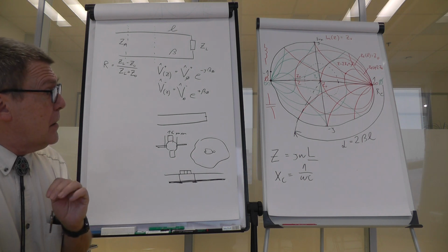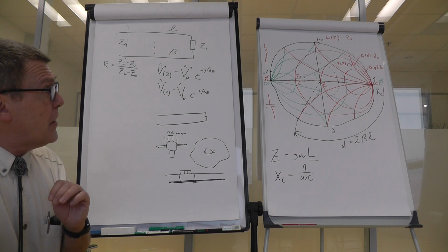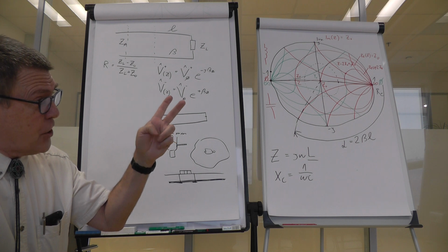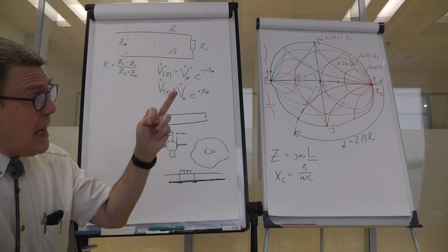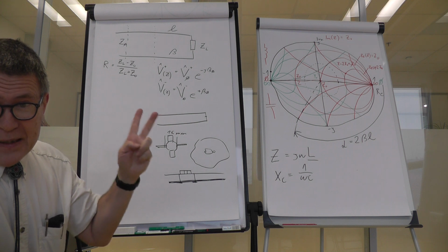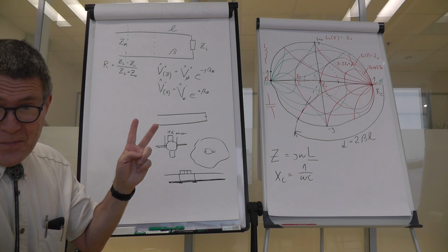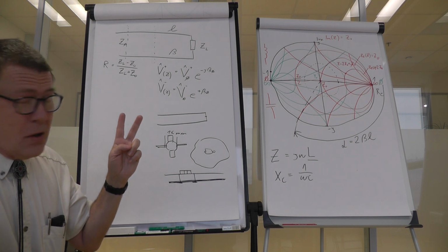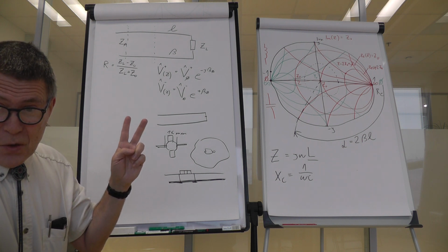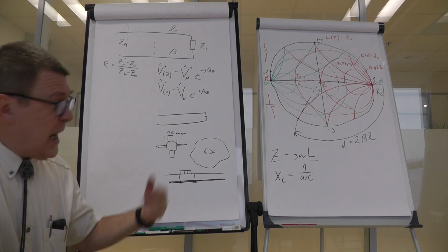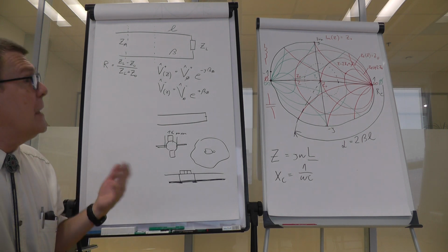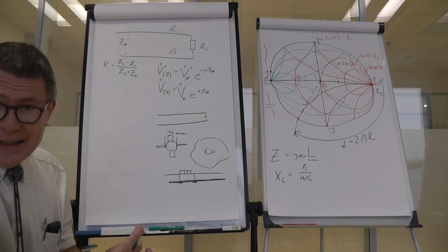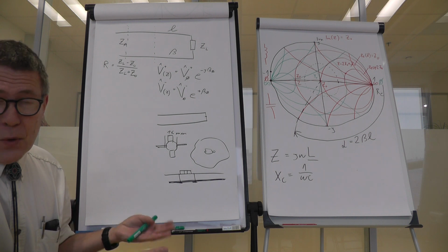Why? In order not to have three sets of lines, that is reflection, impedance, and admittance, only impedance and admittance are plotted. This is because those two are not linear, so it would be difficult to guess the values. On the other hand, the scale for reflection is linear, and therefore you do not have to plot it.